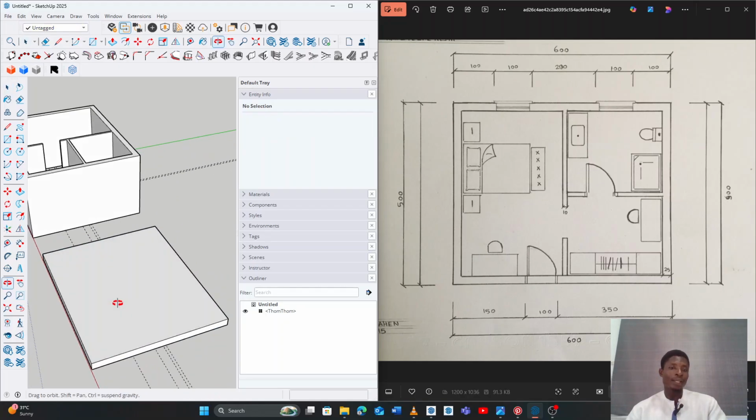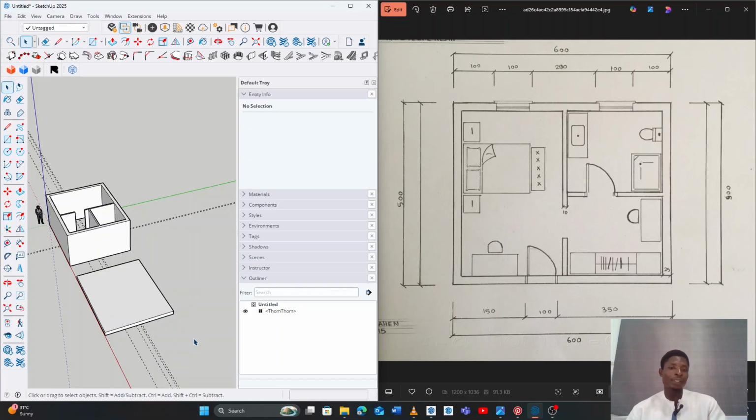Or another way to select an object in SketchUp is you press the left button, and as you are pressing the left button, you move your mouse cursor. As you move it, you see dashes that form a square or rectangle on your screen. That is telling you it is a selection box. Once you move it across the object, that object becomes selected for you.